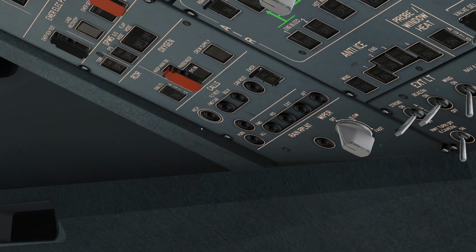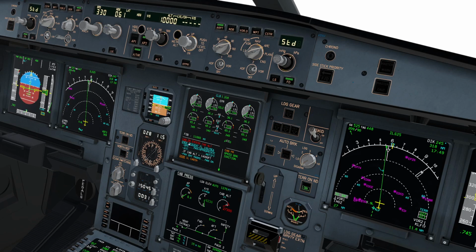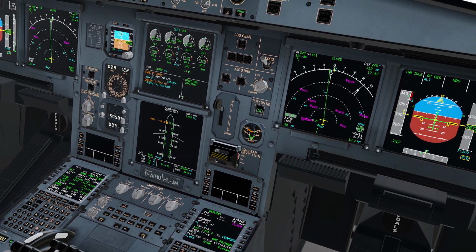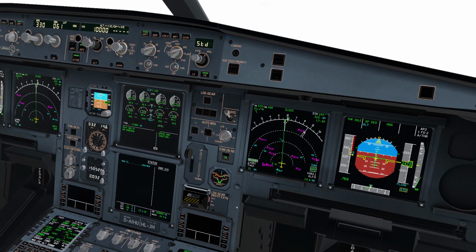On. Okay. ECAM actions complete. Actually, no. Clear cabin pressure. Okay. Door. One left. Cabin. If abnormal cabin vertical speed, max flight level 100. We had that. Clear door. Cabin pressure. Low differential pressure. Expect high cabin rate. Clear cabin pressure. Status. Okay. Stop ECAM.